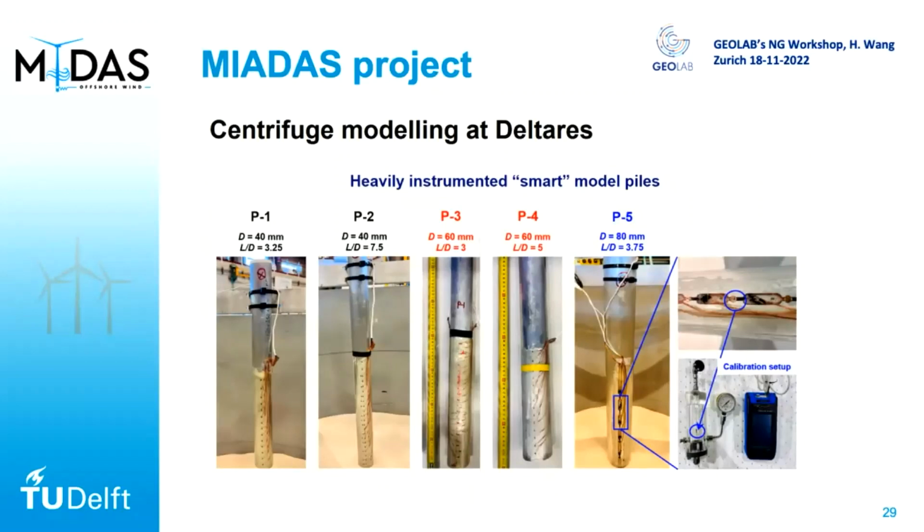Yeah, because in the centrifuge we instrument strain gauges, and then we put epoxy to protect the strain gauges. So we have a different kind of interface between the soil and the aluminum pipe. For this epoxy, we did some interface tests before. The friction angle is different from the aluminum, but it's quite close. And for the lateral response of the monopile, we also did some numerical simulations. The influence of the interface roughness in that range, even a very big change, doesn't really affect the lateral response that much. But I guess if it's a vertically loaded pile, it becomes more important.